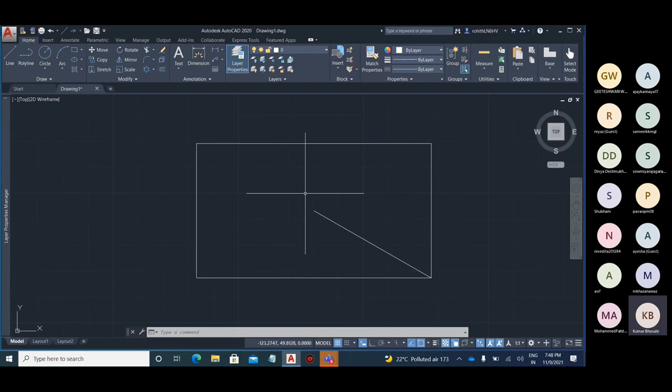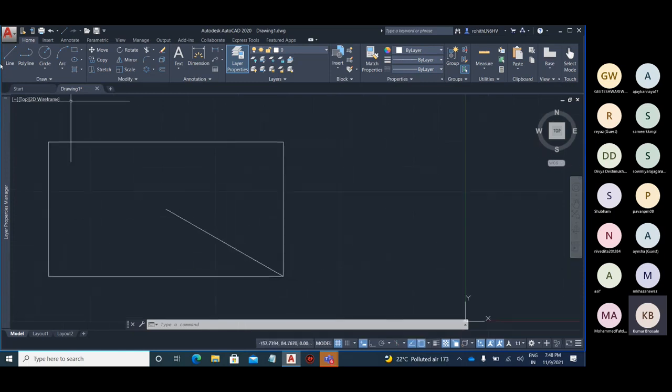That is your object snap tracking. So from the objects we have snaps, and from those snap points I have the tracking lines. To show you this again, you can see I have a green line that is known as object snap tracking. Let's say from this corner point, at a distance of 100, I want to start creating a line.